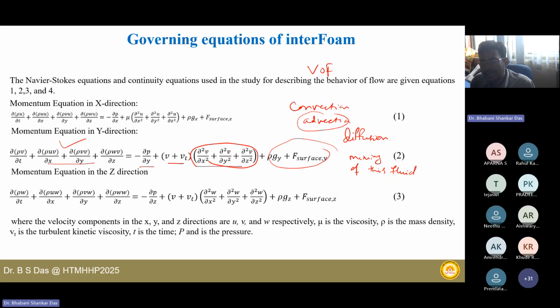Convection and advection are both fast processes, because there is no mixing. They are just traveling from one position to another position. That is convection and advection, so those are faster. But the mixing diffusion process takes longer durations. The eddy viscosity, the turbulence, those are the mixing things. In turbulence, the air and water get entrapped and travel in circular or helical motion, giving a vortices-like pattern. That is handled by the eddy viscosity term, the diffusion term. So those are the physics behind the Navier-Stokes equations.